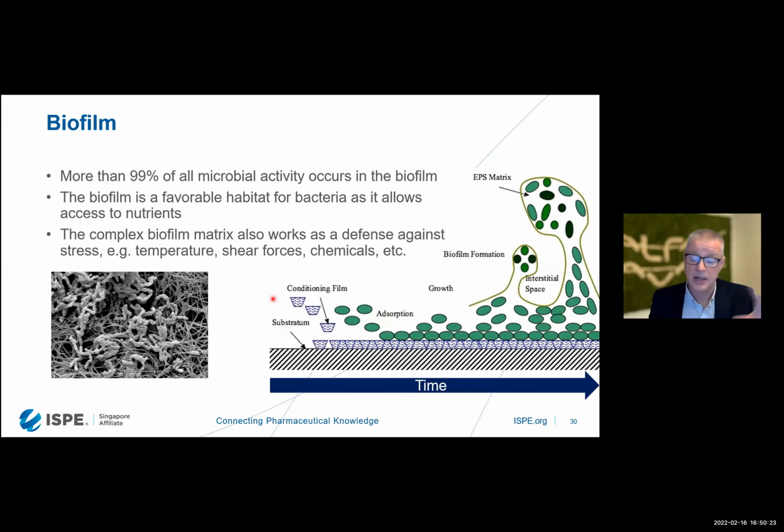In ISPE and in others, they also talk about the biofilm. And we know that all the bacteria, or 99% of all the bacteria activity, occurs on the surface in the biofilm. And there is a risk that this biofilm could be an insulator against the high temperature. But if you have a stainless steel system, you're heating up the surface of the material as well. Stainless steel is a very good conductor of heat. So the heat comes both from below and from the top. So you will still get quite good sanitization of the biofilm if you're using a stainless steel system.